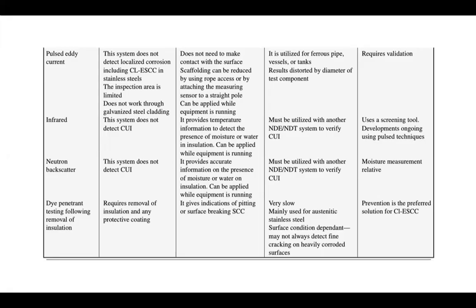Okay, and next, infrared. Limitation: the system does not detect CUI. The advantages: it provides temperature information to detect the presence of moisture or water in insulation. Disadvantages: must be utilized with another NDE or NDT system to verify CUI.